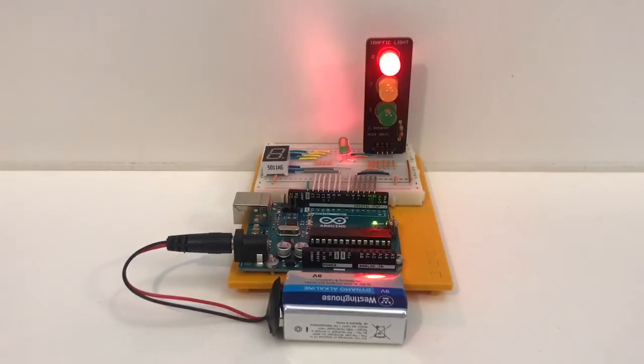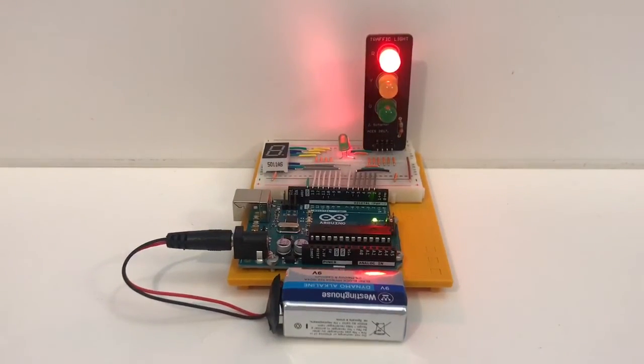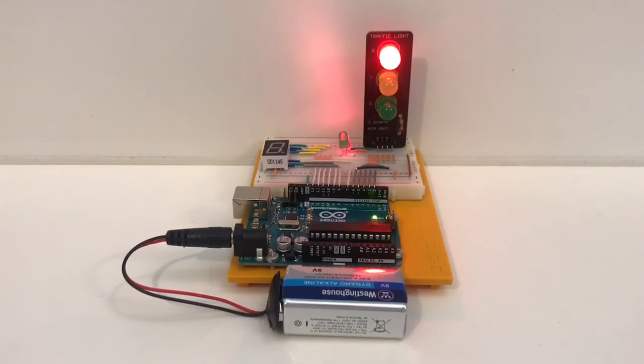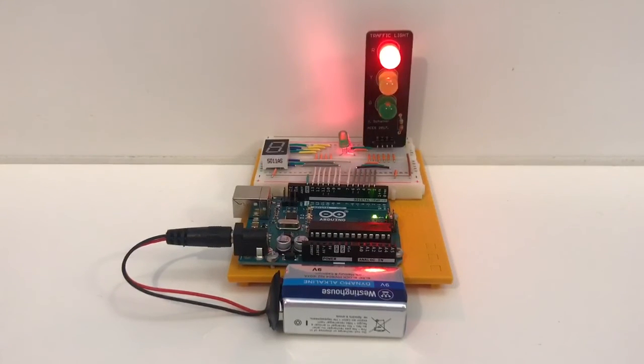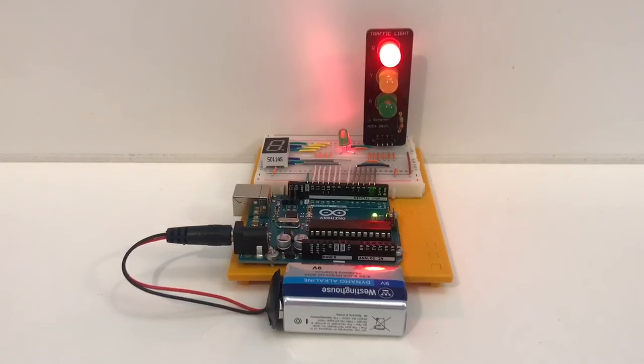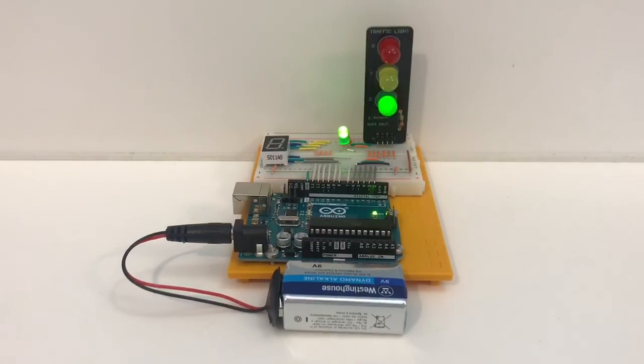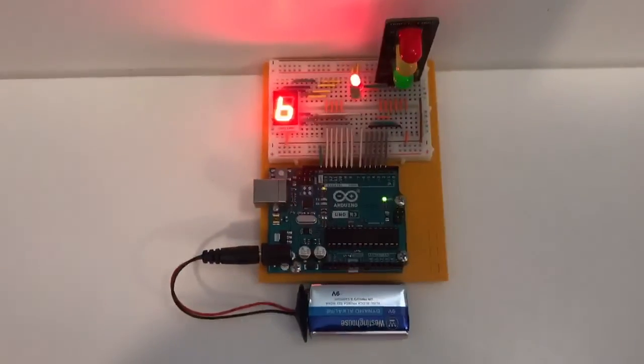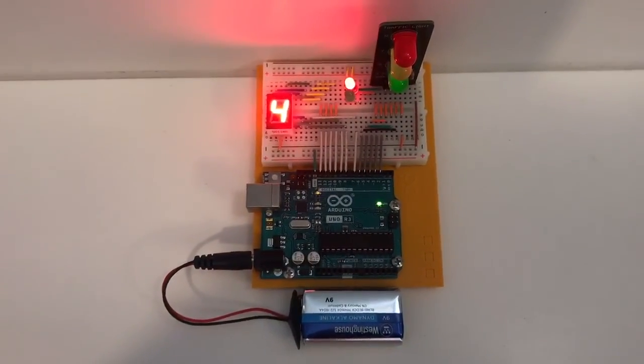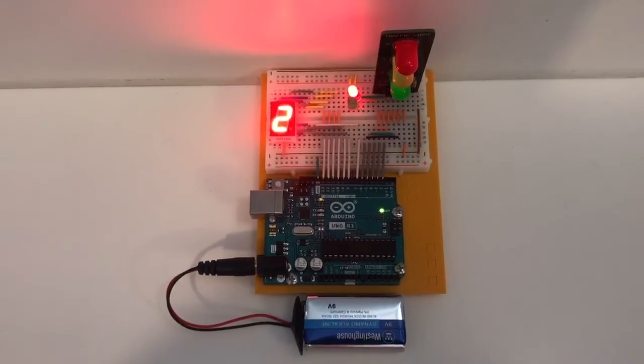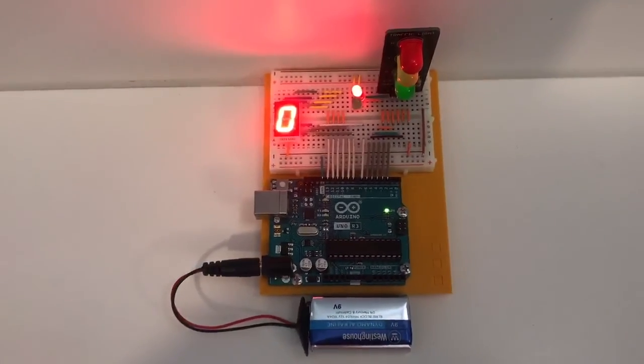The 7-segment display used for the countdown is controlled by assigning each pin from A to G, or 13 to 7 on the Arduino, with a high or low value to display each number. The traffic light was given a high signal followed by a delay to illuminate for 10 seconds on green and red LEDs and 2.5 seconds for the yellow LED. Along with the traffic light and the 7-segment display, this project used a green and red LED to represent a pedestrian crossing light.